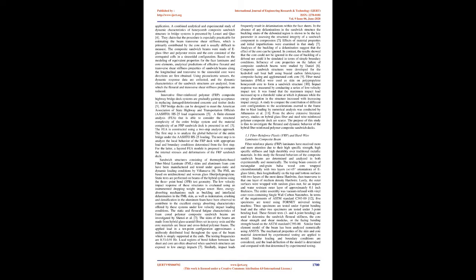The panels consist of GFRP laminates and foam core sandwich where top and bottom skin GFRP layers are connected together with through-thickness fiber. The innovative core design provides an additional strength and stiffness over traditional foam core sandwich composites. Methods of assessment of the material characteristics in tension, shear, and flexural are studied. Various means to test, design and optimize FRP sandwich panels are reviewed. The influence of the thickness of the panel, presence of filling material and density of 3D fiber insertions are also discussed. The feasibility of glass fiber reinforced polymer, GFRP, systems for low-profile bypass roadways was investigated by Rocca and Nani 3.